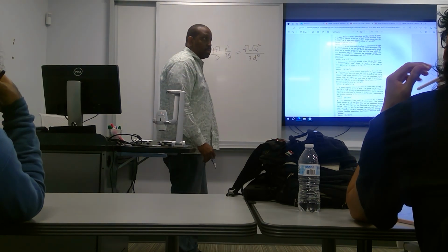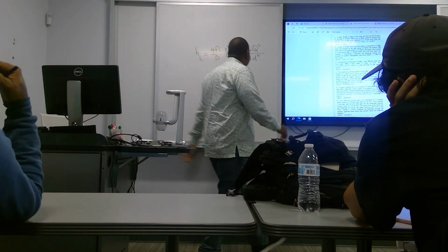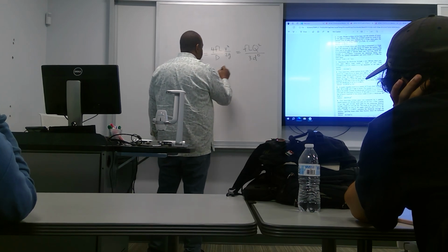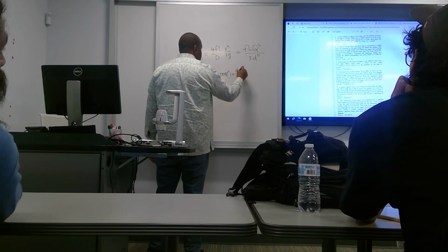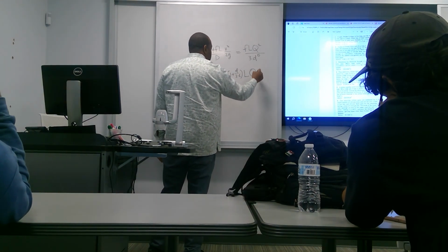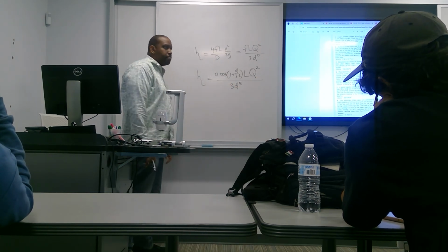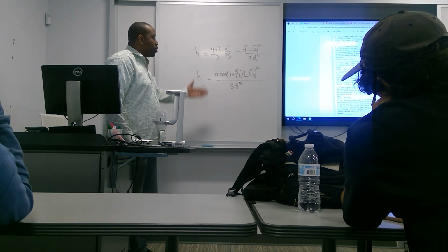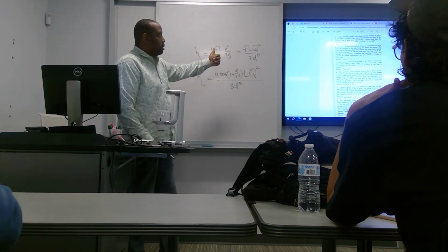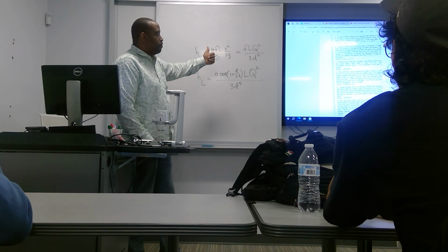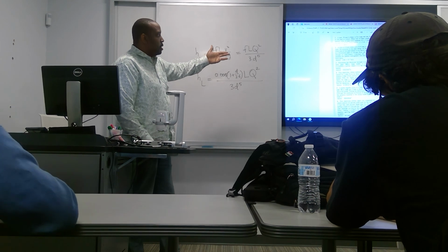Okay, so we have an expression for F. Now our head loss becomes this new F, 0.005 times 1 plus D on 3.6 by L, Q squared over 3D to the 5. So now we plug everything in there because we have D. You have both D1 and D2. You have D and the length.